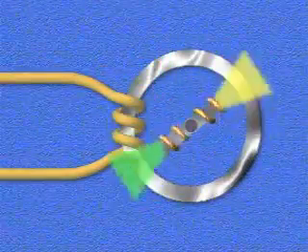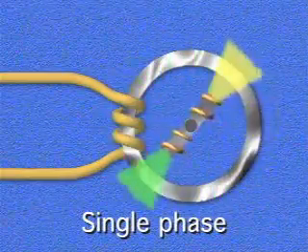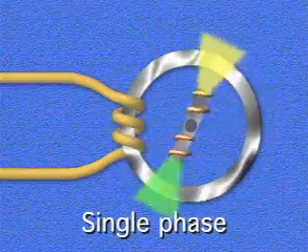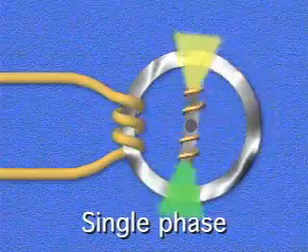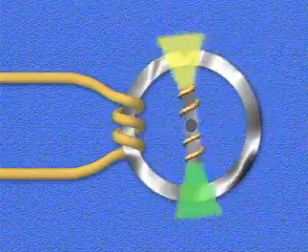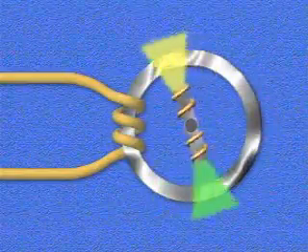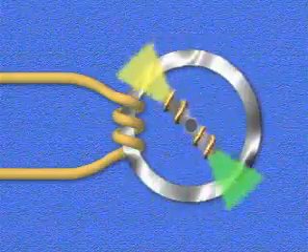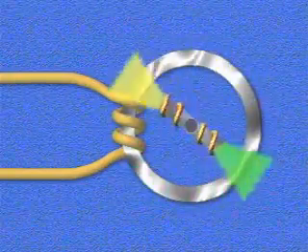The output from the generator we've been looking at is single-phase voltage. Single-phase means that there is only one voltage output. This is because our example has only one stator winding or conductor. However, most generators used in power plants are designed to produce three-phase voltage. Let's see how a three-phase voltage output can be produced by modifying the simplified generator illustration.